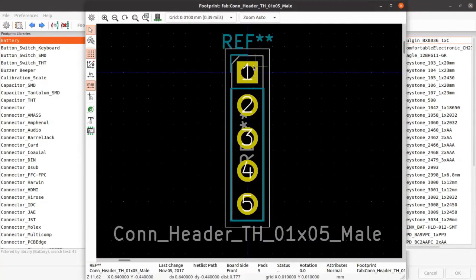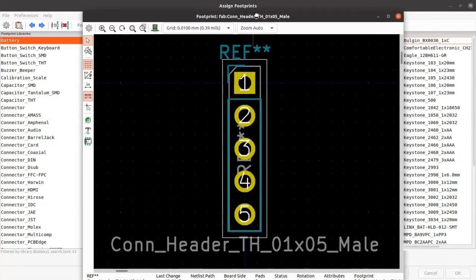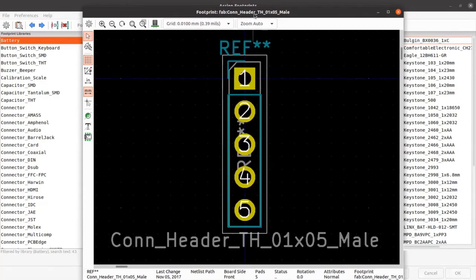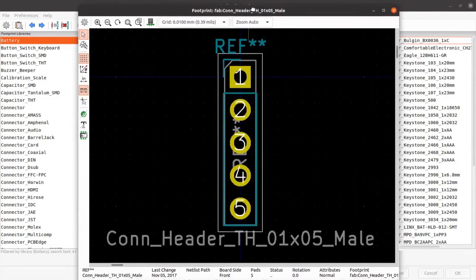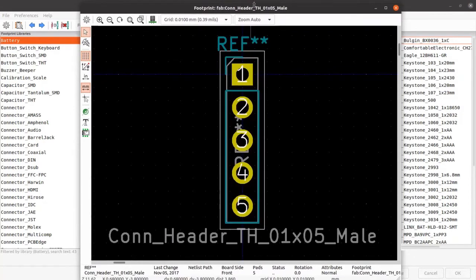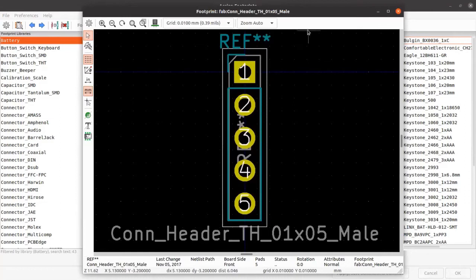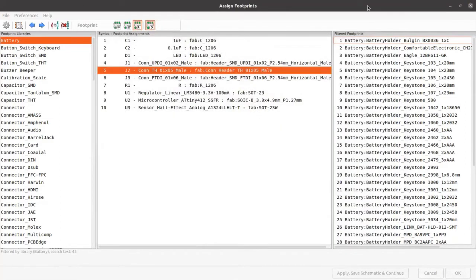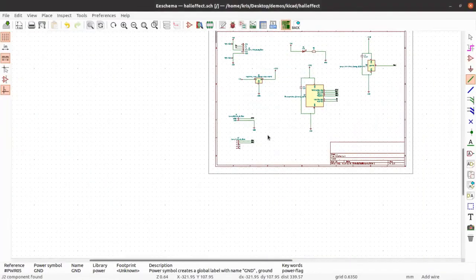These through-hole headers are designed with the thing in mind that you need to drill 1.5 millimeter holes in order to be able to insert the 1.5 millimeter rivets into them. I actually have a few unedited videos that have to be edited this week, which show how to use a different software other than mods to do this in a much easier way. So I will notify you once that is done. And then we can move on to the PCB part.